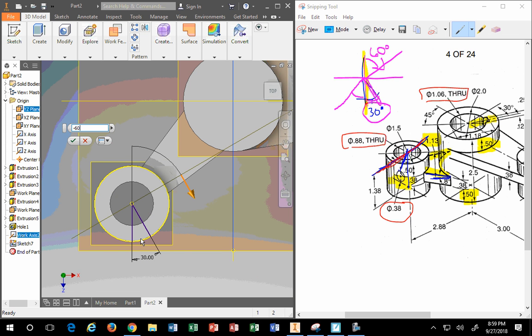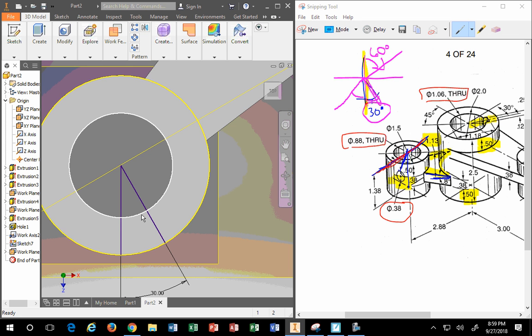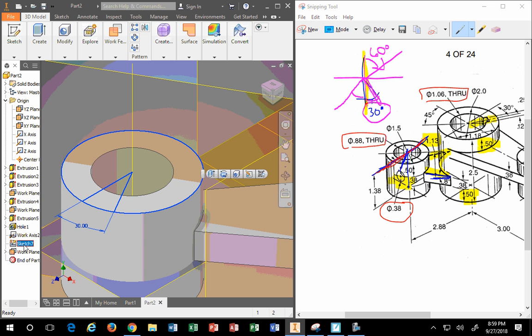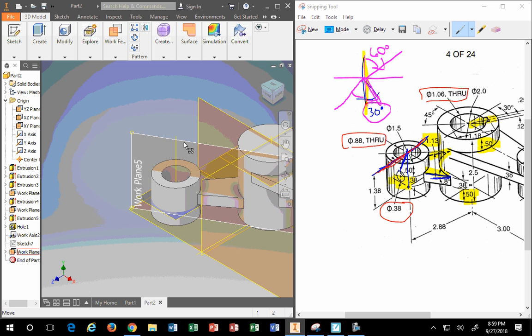See it? So I don't need to make two planes to get this done. I just need to know my math, my dimensions, the geometry associated with what I'm making. And even if I don't have a clear picture on that, if I put in a reference sketch for myself, the same way I had you do in the other drawing, that reference sketch helps me build this thing, because I know where I'm going. So you don't have to guess at it. You can always take the sketch and just not have it visible anymore, because now my plane is the correct orientation.